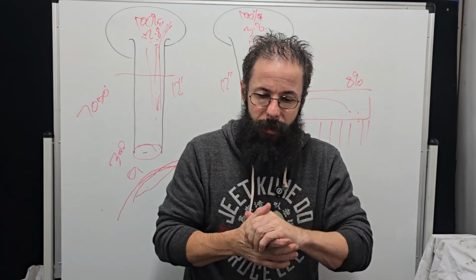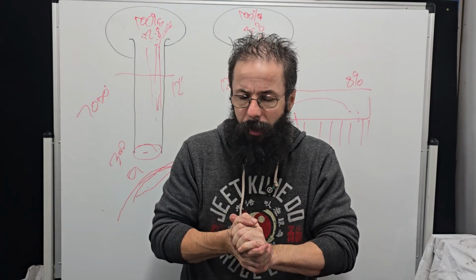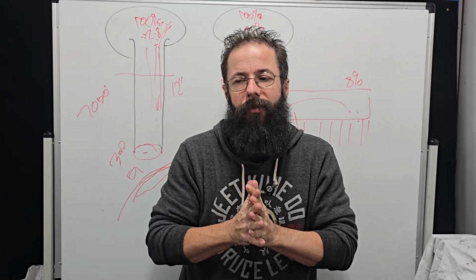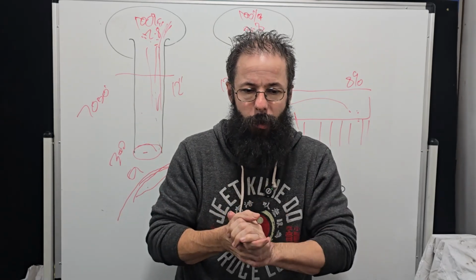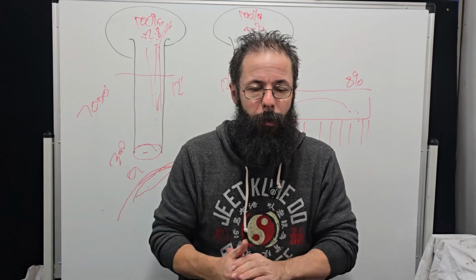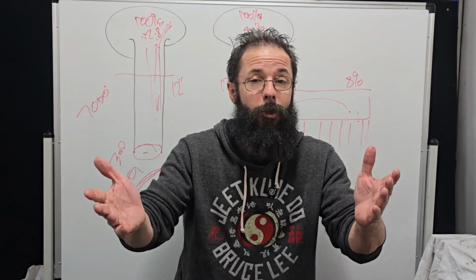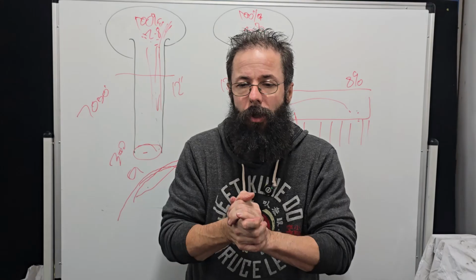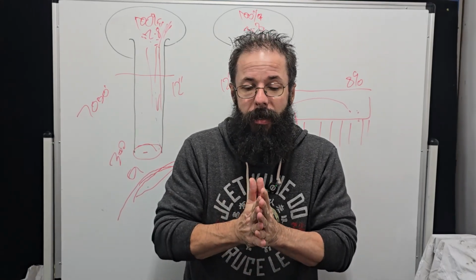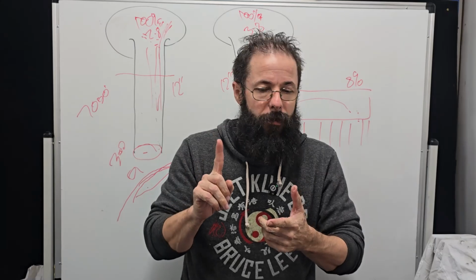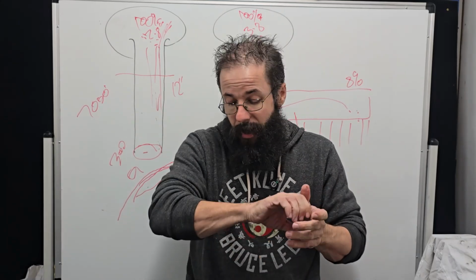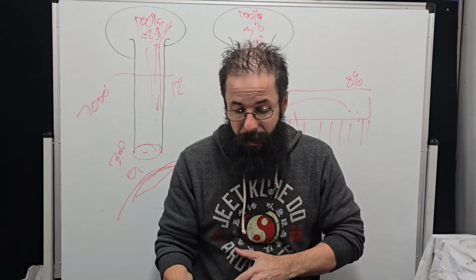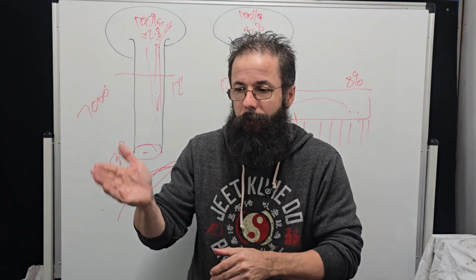And again, I was talking to a guy about exhaust, and he said, oh, I'll just dent the exhaust. It'll make no difference. I've seen it on Engine Masters. I think that's the one where they had four dyno pipes they put on the engine, found the closest one and dented it, and actually made horsepower. And then the conclusion was, well, dents really don't matter too much. And that's totally false. The reason why it's false is simply that, one, they didn't spend the time. They didn't spend three weeks like I've done making an optimal pipe, finding the best size for the pipe on the dyno, finding the best step, and then denting it. They just found an average pipe that worked better.